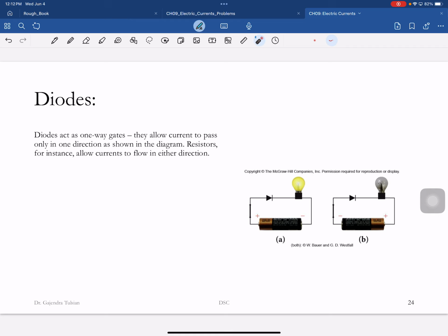And so essentially, the way the diode works is if this end is about 0.7 volts above this end, its resistance goes to 0, it essentially becomes an open gate and current flows this way. If it's less than 0.7 volts, then it doesn't let through current. So if this was 0.1 volts and 0 volts, it's not an open gate anymore. And of course, if it's negative voltage, then it won't let any current at all. So the diode is a one-way gate essentially.